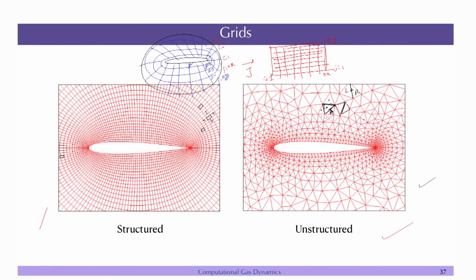So, for example, in this if the flow is coming from left to right, you have to be a little bit careful. It is not as trivial as a simple grid like this where the flow is coming from left to right, because your elements are in this direction for example. But still you have an overall picture that if you can convert to this grid, or if you find the face normal, you can basically define which direction the flow is happening, and you can accordingly apply the upwinding here, upwinding there.